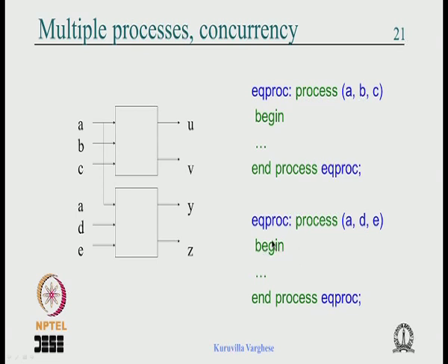So with that I would like to wind up. Today's class we have looked at the different models of description, and we have seen the data flow model using concurrent statements like when-else, and also the data flow model using equations, and we have seen that when-else is much better than equations. Then we looked at concurrency: if you write 2-3 statements, the simulator has an issue if the order is not correct, it has to resolve concurrency, but for the synthesis tool it doesn't matter, it looks at the description and generates the circuit.